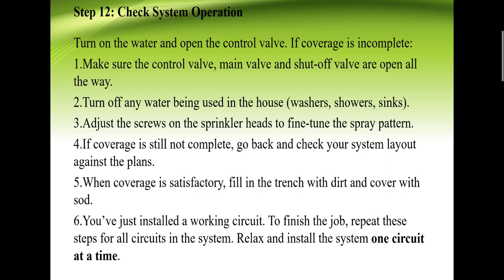Adjust the screw on the sprinkler heads to fine-tune the spray pattern. If coverage is still not complete, go back and check your system layout against the plans. When coverage is satisfactory, fill in the trench with dirt and cover it with sod.